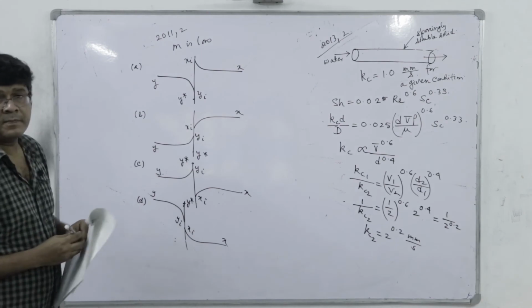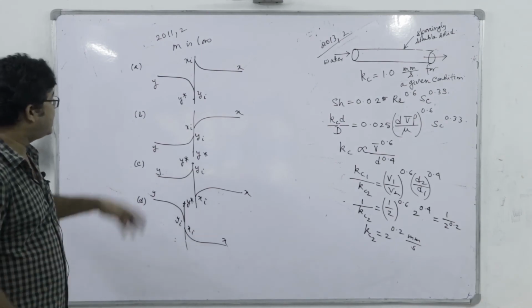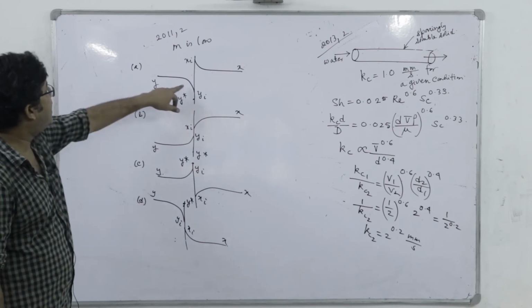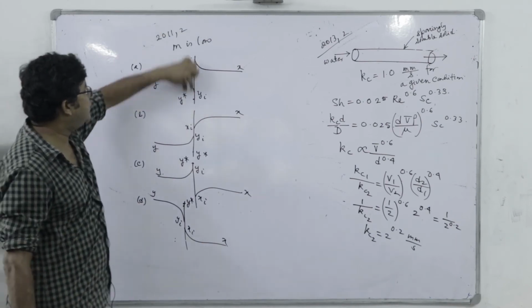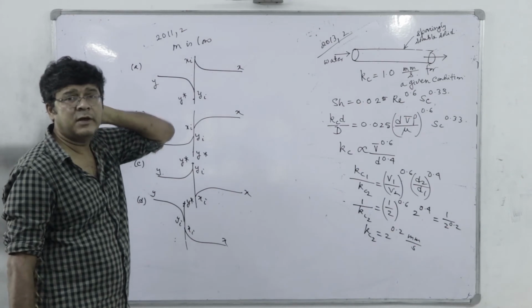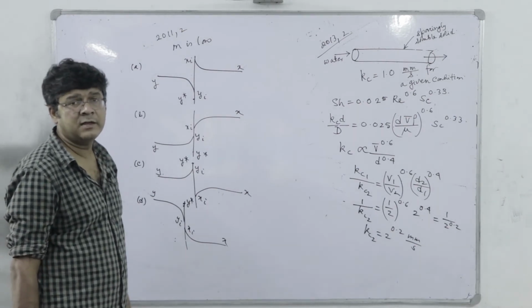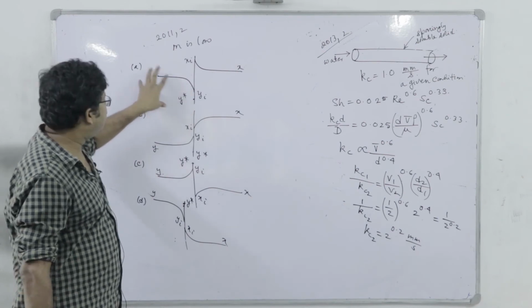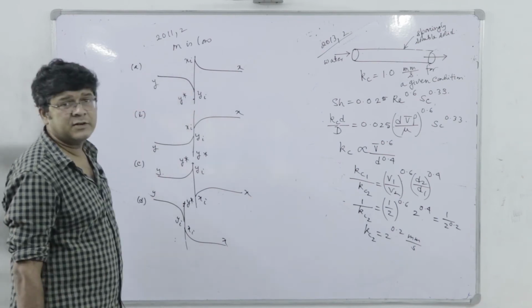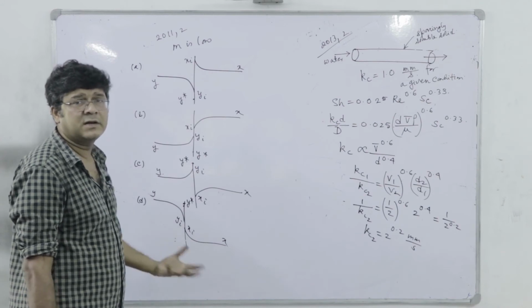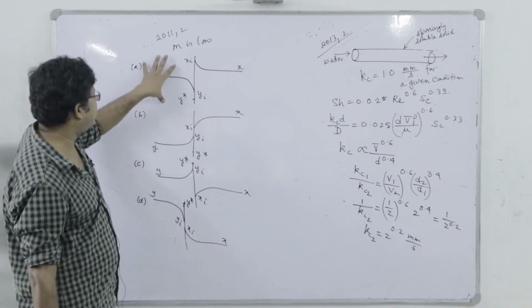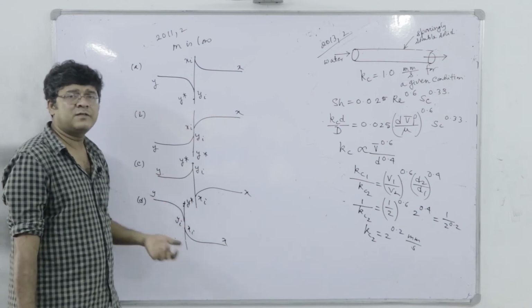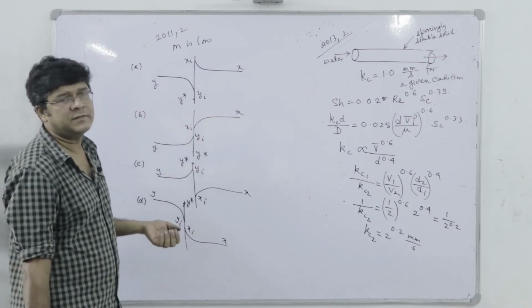Now you see that close to the interface concentration must undergo a fall, right? Why is this fall necessary? Because close to the interface we have a laminar sublayer where the resistance is pretty high, because it is diffusive resistance, and far away from the interface we have turbulence, so it is more majorly a convective resistance. Convective resistance is much lower than diffusive resistance.